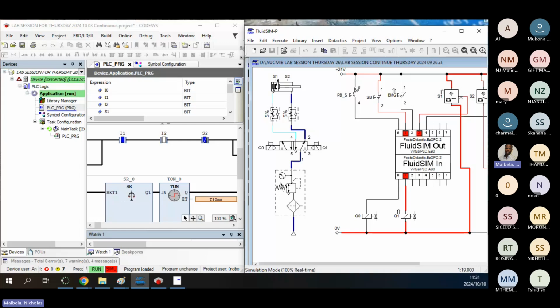Nothing will ever happen. Why? Because your emergency stop button works differently to a normal stop button, in a sense that you have to always reset your emergency stop button. So if you can observe there, your emergency stop button now is normally opened, right? That contact is not closed fully. So once you reset it, as you can see, it's closed. And the other thing you can observe is that if it's opened, the number two port there is white.